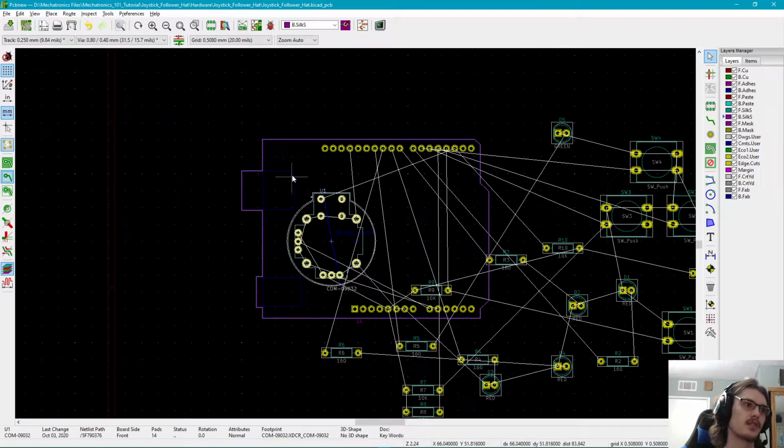Anyways, this is a port that has some volume that would extrude from the board and possibly interfere with any parts that would be on top of it. Additionally, this is a 9-volt input of the Arduino, and it also will extrude out from the board. So we have to avoid overlapping stuff on it because they would collide and you just wouldn't be able to plug it in together.